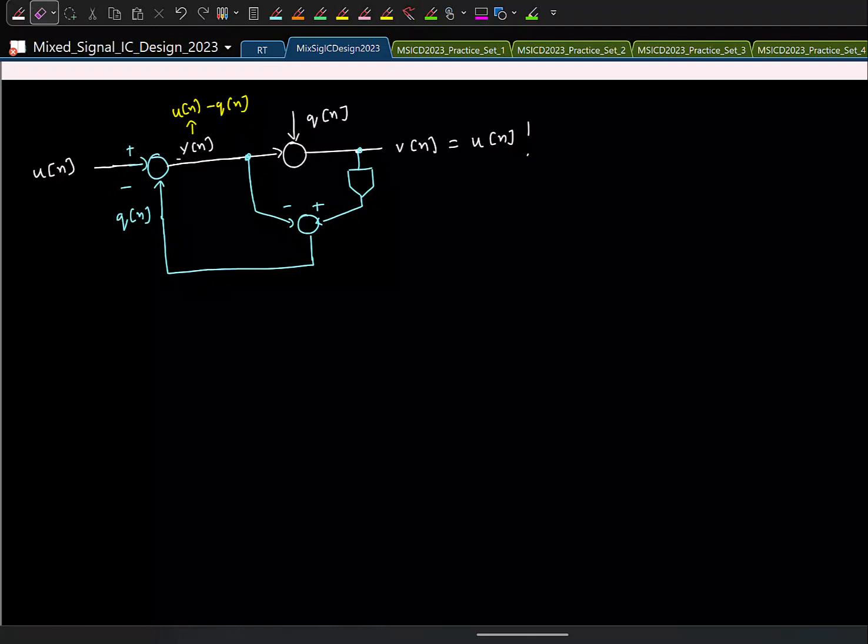So in this entire business, I will have one clock cycle of delay. Is that clear? I will digitize the data, get what q of n is, and I can use that information only in the next clock cycle, as an estimate. So this is going to have one clock cycle of delay. I will model it as Z inverse. Is that fine? Z inverse models one clock cycle delay.